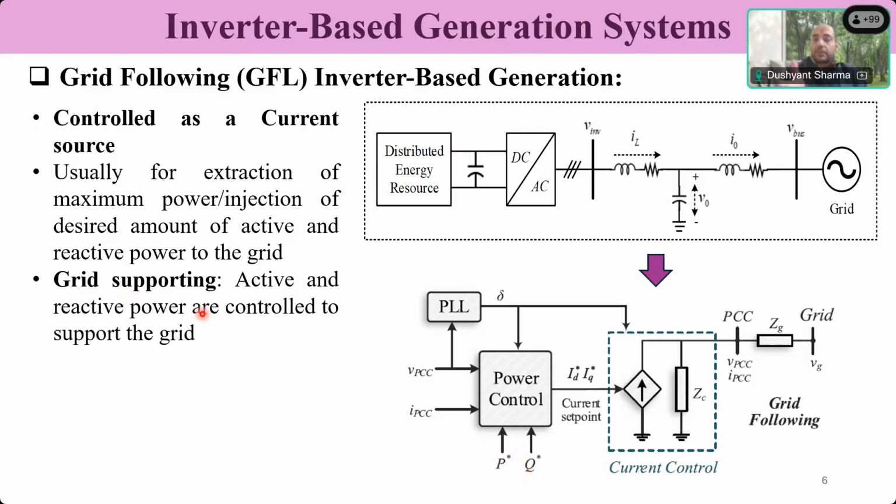So it's basically the same thing: you have to control the inverter in a grid connected mode, synchronize at the point of common coupling, and inject a current in the desired phase to get the required active or reactive power. Now, this is achieved by a controller. As I told, an inverter by itself doesn't have any physical law to follow.